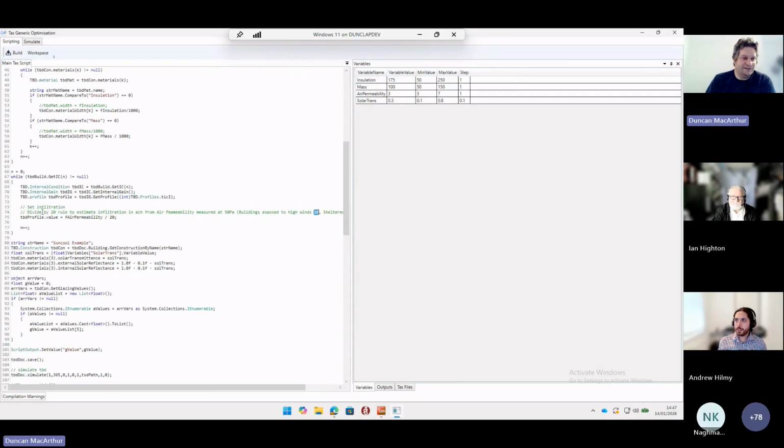The other thing is, based on your air conditioning system, you might expect that when that's on the infiltration drops, so there's lots of different options there for how you want to model the infiltration. But I've just set an air change rate, and that will be all the time for the zone.